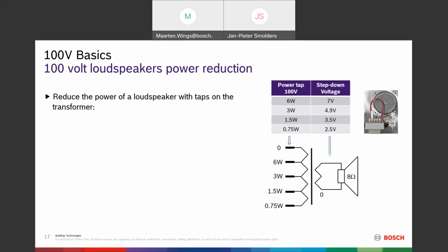There's another thing with those transformers. The transformers sometimes have, well, in most cases, all of our loudspeakers will have this. If you look at the transformer, you can see some taps. If you look on the right side of this picture here, you can see some taps, some outputs on the secondary side of this transformer, and that means that you can tap it down in power. So each tap that you go down, the power that this loudspeaker will consume will be reduced by 50%, so half the power.